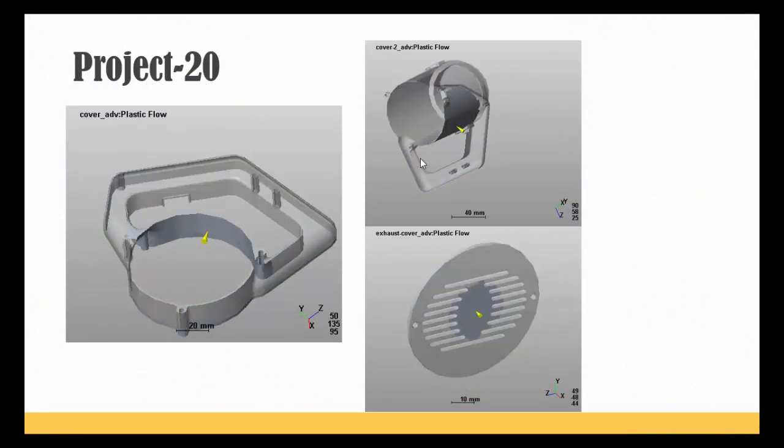And not only the filling process, you can also optimize the overall location of the gate where it is performing better and filling time is optimized, and as well you can go for a typical case study. If you want to try three different gate locations and go for that in the real world without having a virtual simulation, you just waste your time and money and everything. So what you can do is go for a case study in three different scenarios to see where I'm getting the best result, and that I can map.